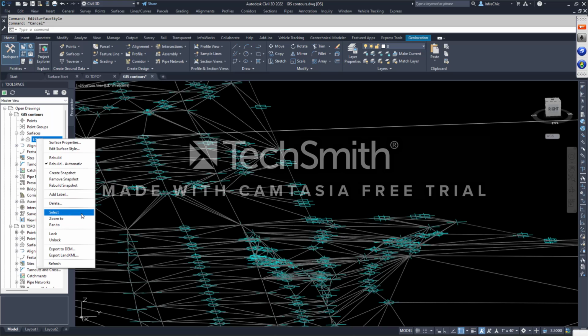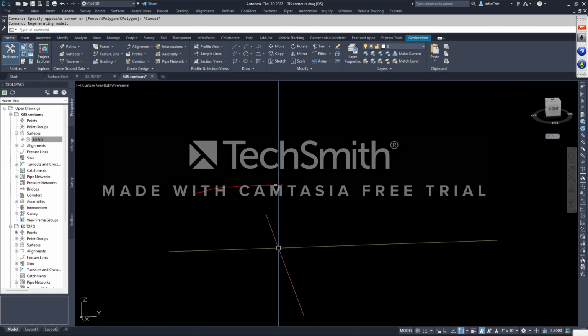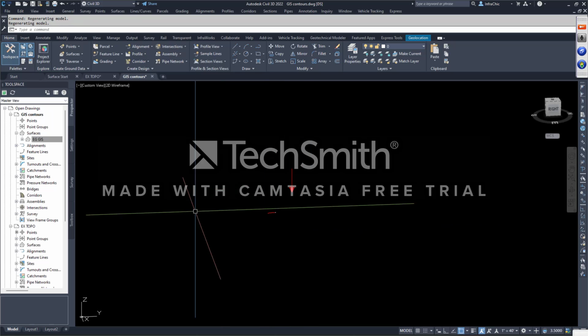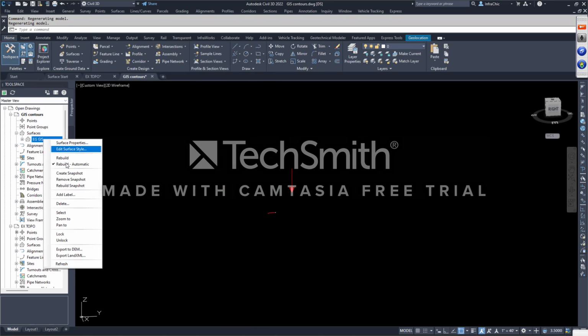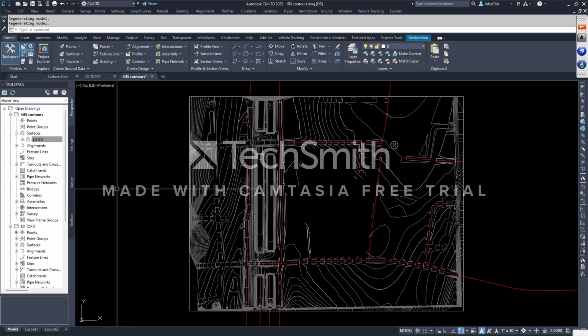I can zoom to, so if I can't find my surface, I'm out here in outer space. I'm just going to do that. Get way out there, right? There you go, outer space. I right-click on my surface and I say zoom to. It puts it in a 2-dimensional wireframe, takes it completely out of 3-dimensional that I may have had it in, and it zooms right to it, okay? Quick way to get back to it.